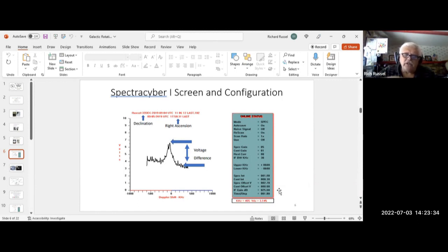So you need to lower it so the peak is within the screen, because that also means it's actually being recorded. If it's flattened on the top, it'll just say 10 across your data, and you'd have to interpolate where the actual peak was. And the peak is what is important here.